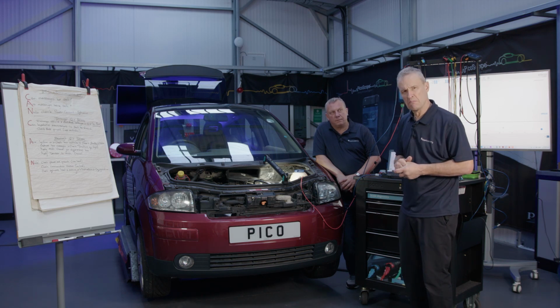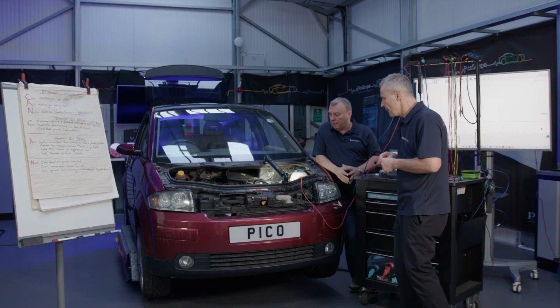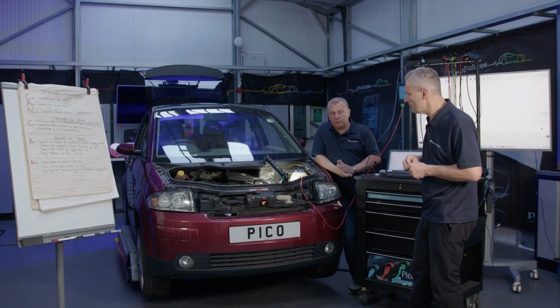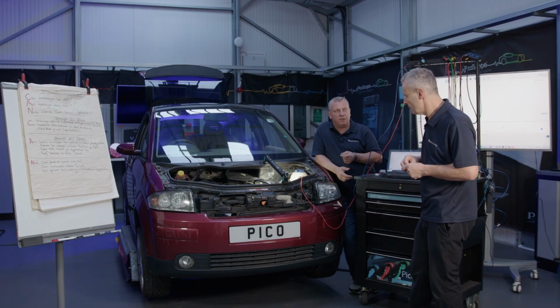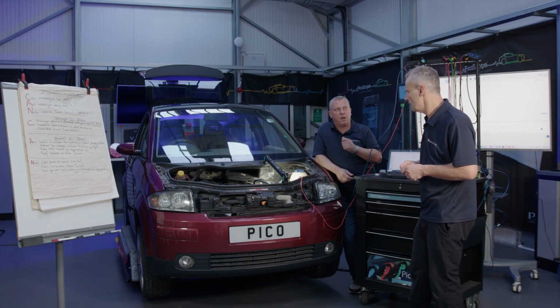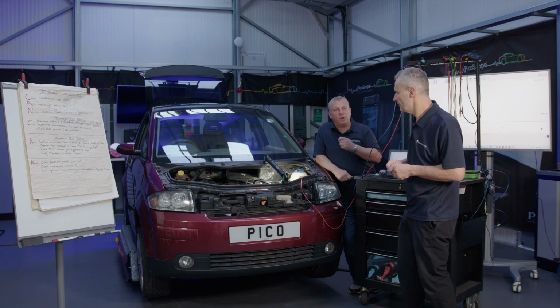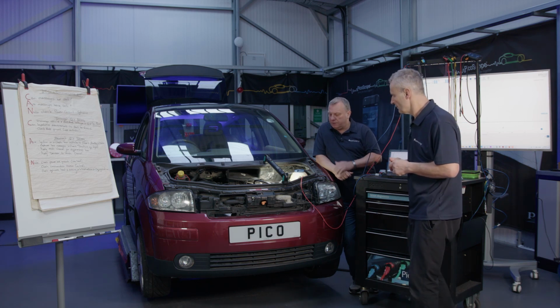Could we test that more thoroughly? You suggested load, Andy. Yeah, typically we would test grounds under load. But because the vehicle is dead and we've confirmed that, if you are in a position where you can't power an ECU because it will not power up, how then could you check that ground? If you suspect an ECU isn't drawing any current, you can't prove the ground using a traditional volt drop because volt drop requires the circuit to be loaded. If you can't load the circuit, then this is the next best step.